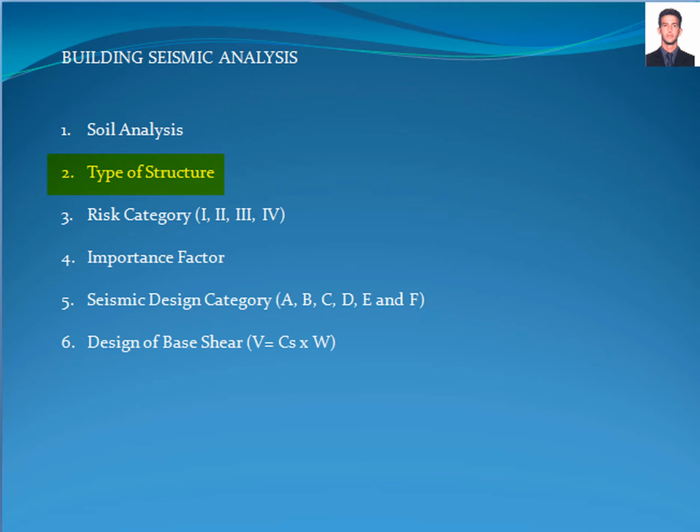building frame system, moment resisting frame system that is subdivided in ordinary moment resistant frame, intermediate moment resistant frame, and a special moment resistant frame. The other systems are dual system with special moment frame, dual system with intermediate moment frame, shear wall frame interactive system, and a steel system not detailed for seismic resistance.